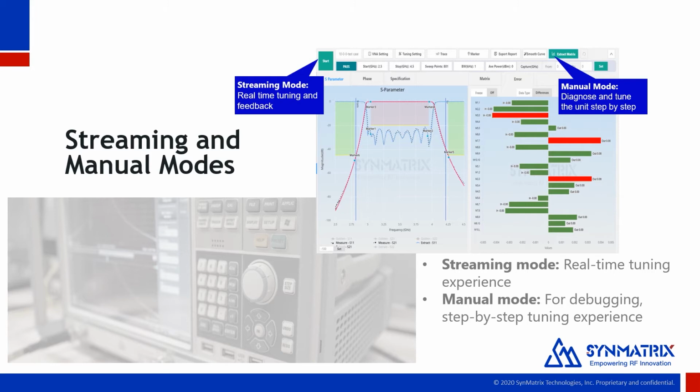The second one is the tuning mode. Different from other tuning software, SynMatrix provides two modes for test and tuning purposes, streaming mode and manual mode. Streaming mode can be used for mature products for real-time test and tuning work, so the end user can apply it to the massive production tuning line. The manual mode is used for prototype diagnosis and allows the user to tune and identify the issue step by step.